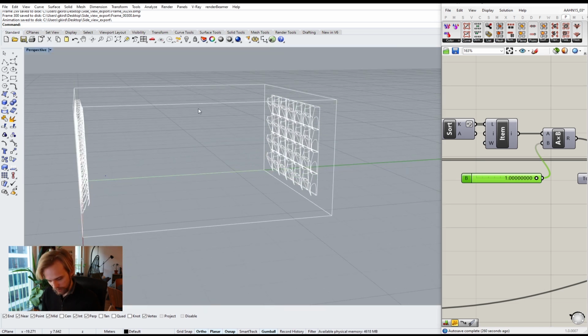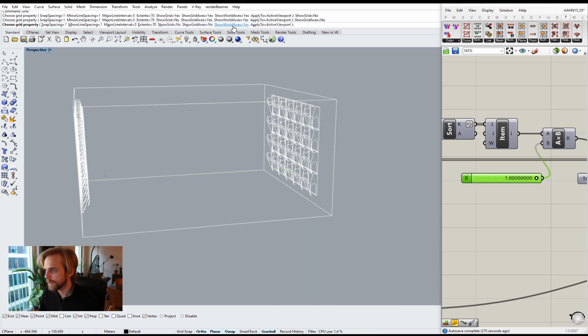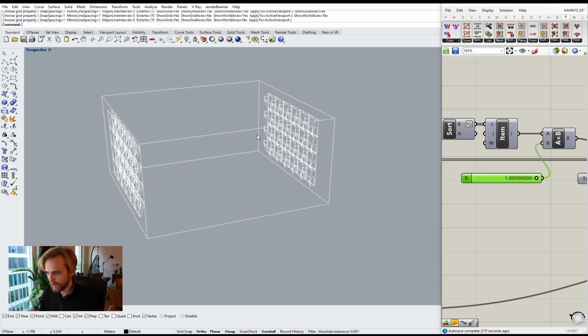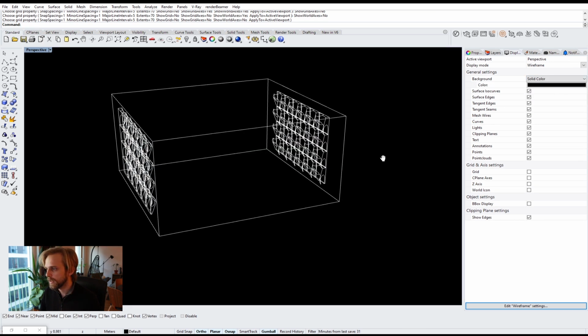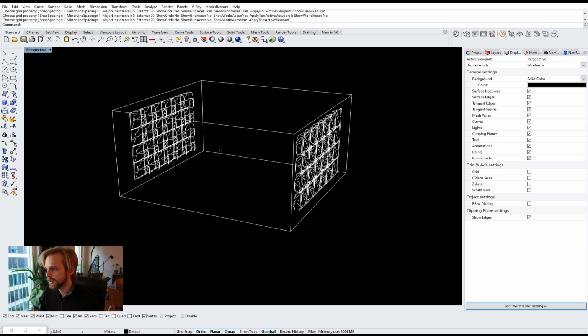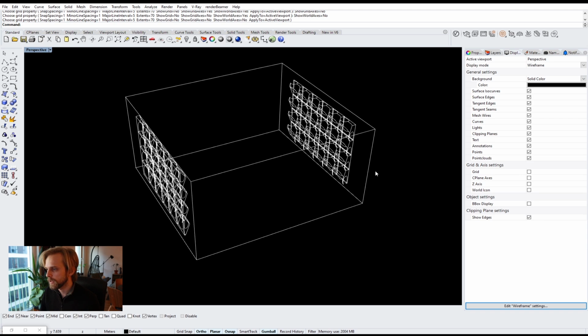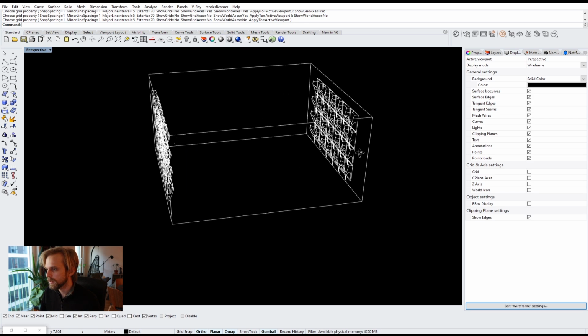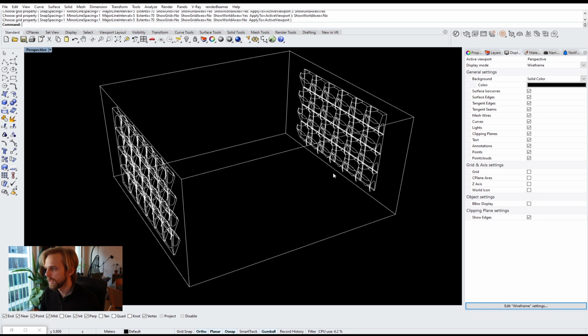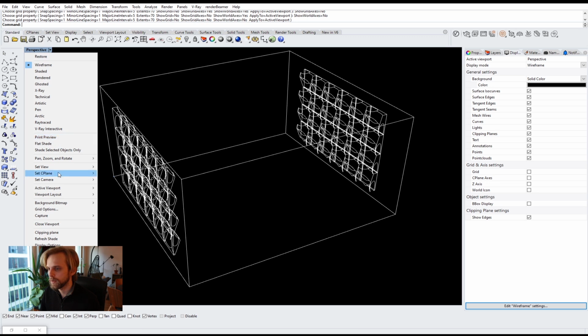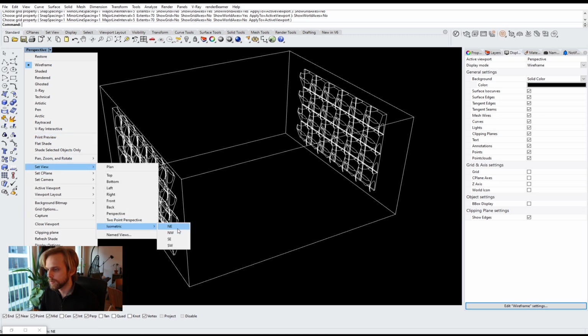I'll do the same thing with the perspective view. So here, hide the grid. Show grid no, show the grid axis no, show wall axis no. The display, solid color black. That's good. Perhaps something like this. Something like this will do the trick. You can do AXO as well if you want to. Maybe AXO will be cool.